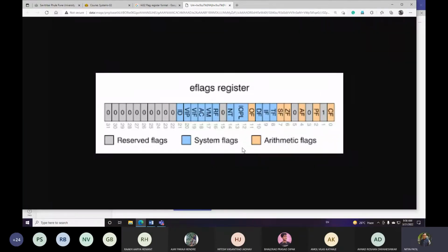This is a 32-bit representation of a flag register. Now these are the positions of those 32 bits for the flag register. So the carry flag would be here. This position is not used. This position is not used. Wherever the names are, otherwise it would be 0 or 1. They are reserved, with the assumption that it will probably require some more flags to be added, and these positions would be given to them.